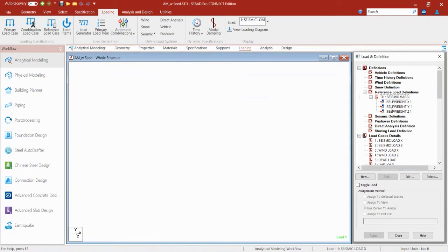I did put some load items within this load case, which you are able to do. Typically, when you close your model and you have, say, a blank load item in it, it doesn't actually write it to the input file. The way you can get around that is you can put this directly in your input file if you feel comfortable with that workflow. So here I'm ready to go.